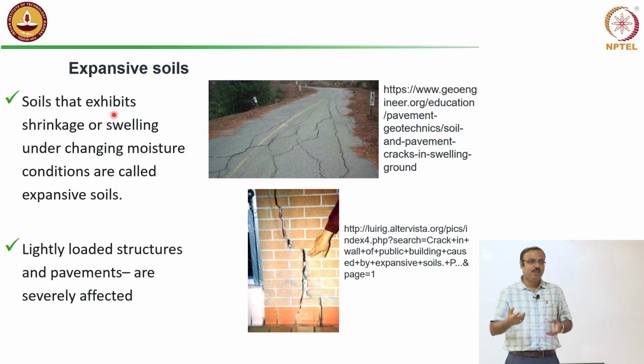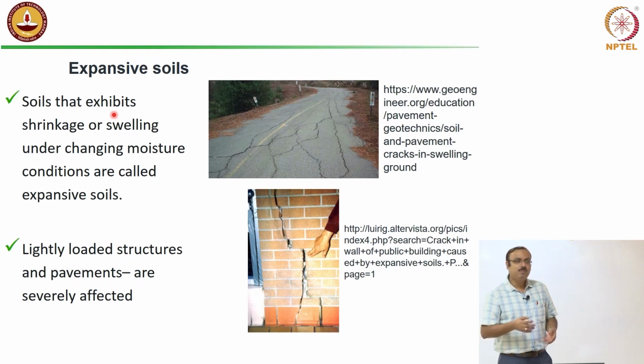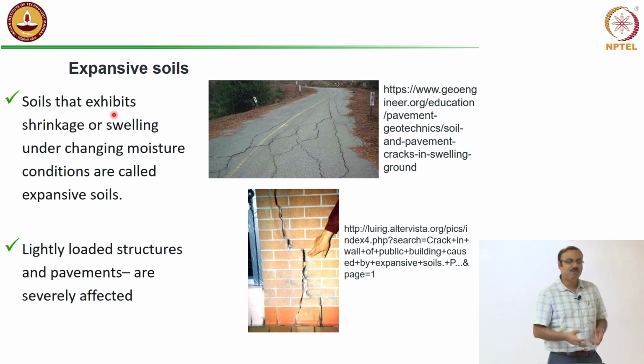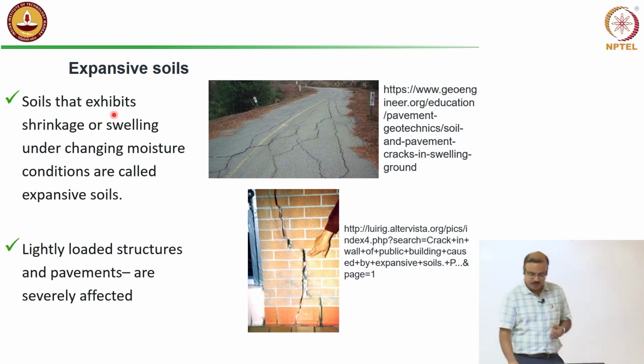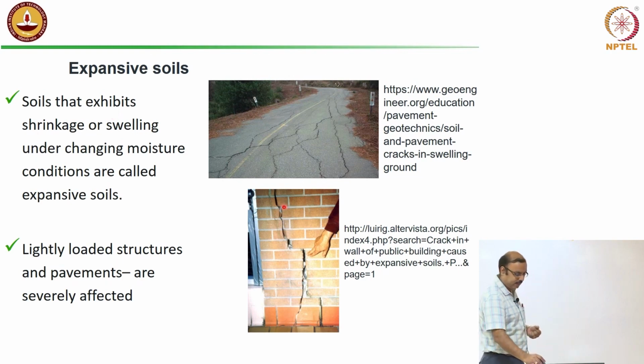This building below, when the volume of the soil increases, we will have an uplift type of pressure, an upward force. Then after 6 months, in the completely dry summer season, the soil is shrinking. What will happen? This building will again go back to its original situation. So, there are situations where the buildings may not be able to take this expansion and contraction of the soil, which may end up with cracks in the buildings, like typical cracks in buildings like this.